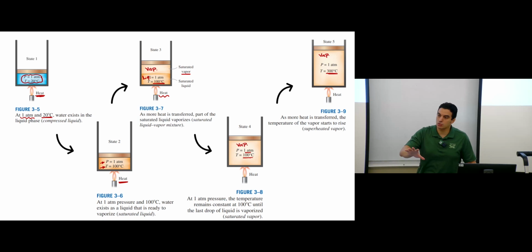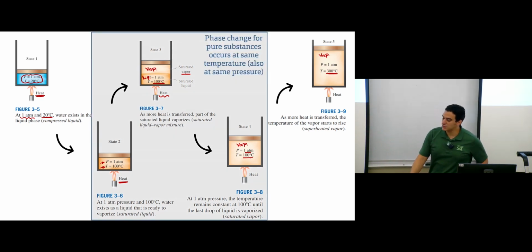This is the same observation you can see for phase change for any pure substance. Mixtures have different behavior. But for a pure substance, we have liquid phase, and then at fixed temperature, at a certain pressure, phase change completely will happen, and then the temperature will increase in the vapor phase one more time. Clear? So this is the key here that describes a pure substance.